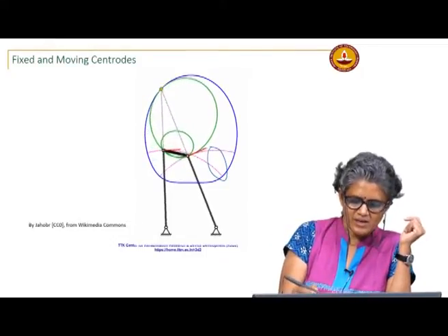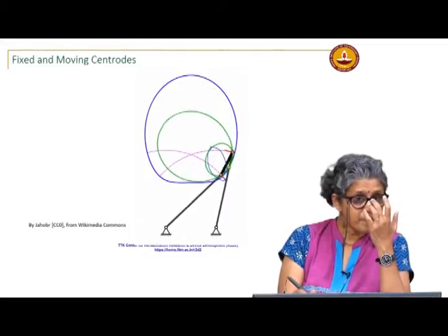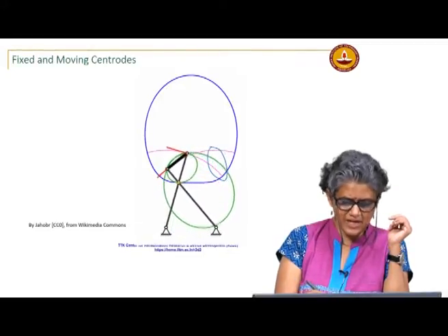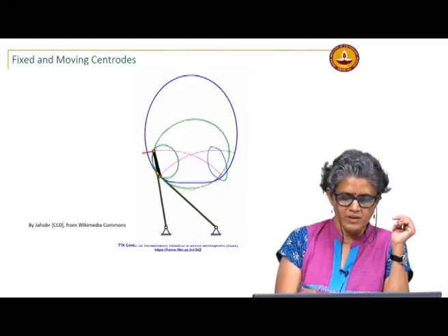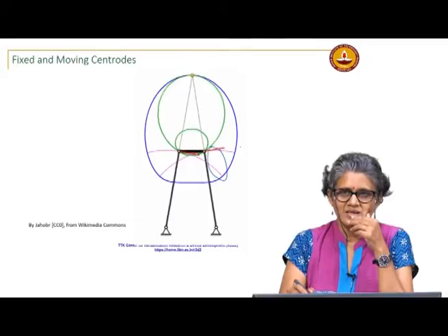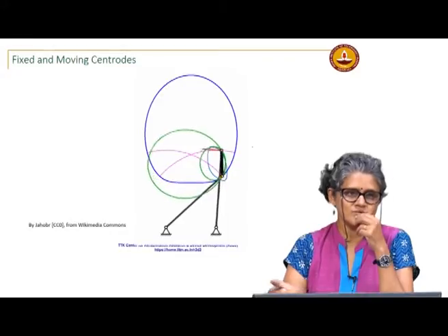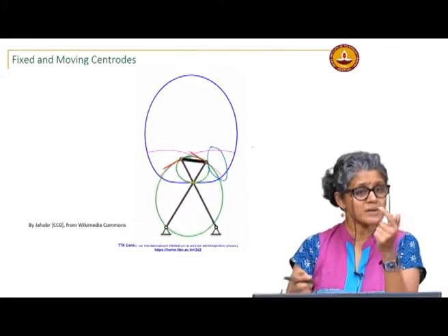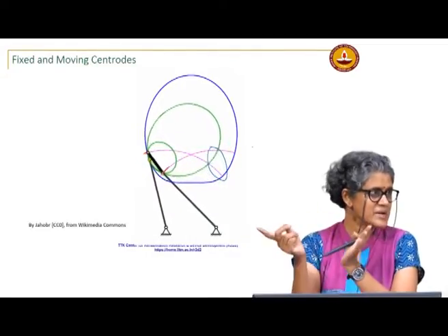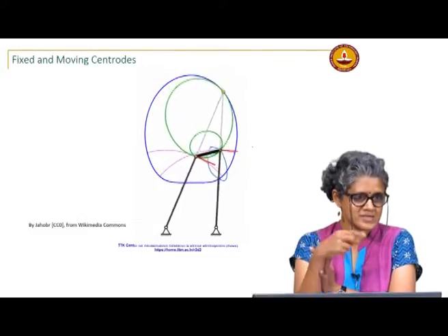That is the point on the rocker itself. This is a point on the rocker, yes. When we plot the rocker's curve, it is changing, that is the magenta. Will it also be considered a coupler curve? That is basically a special point on the coupler, because it only moves along the circular arc. Yeah, that point actually reverses direction at the limit positions. So, if you consider that as a point on the coupler, it is reversing direction.